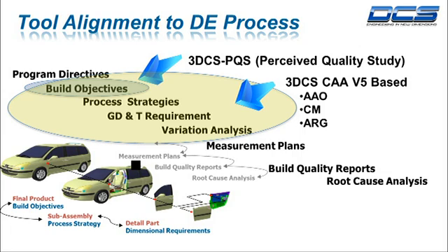And we take into account things that might have impacts, like the effects of thermal change, or the effects of processes like welding, or forces that are applied through clamping and things like that. Those can all be accounted for during the more traditional engineering stage of variation analysis.